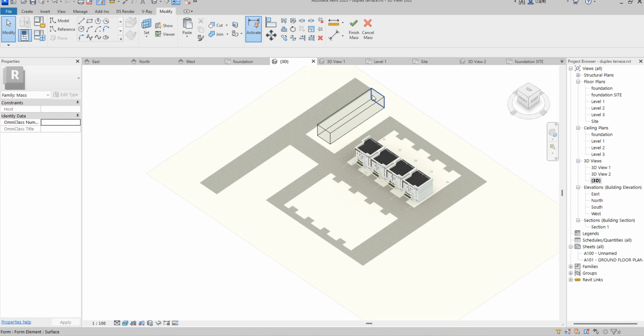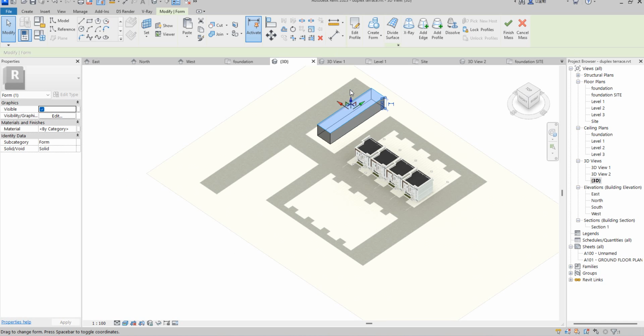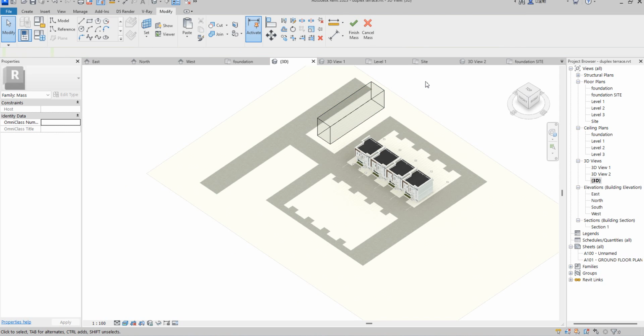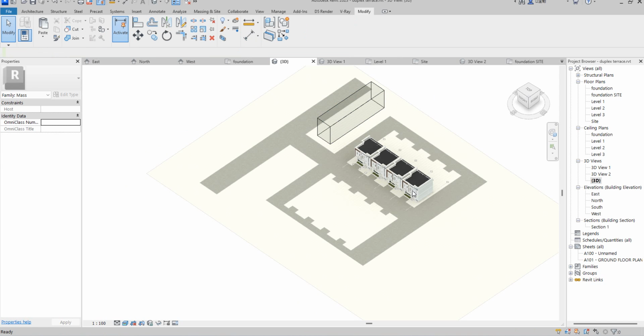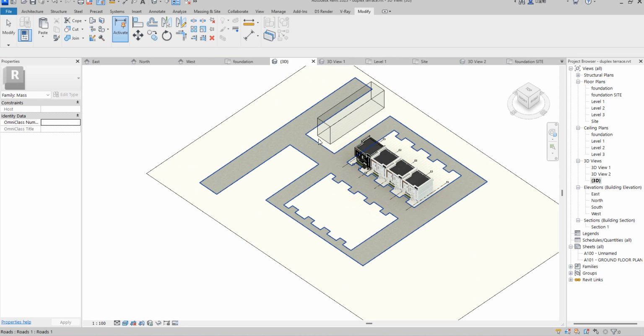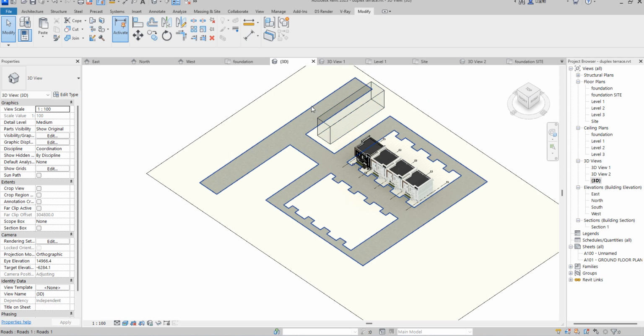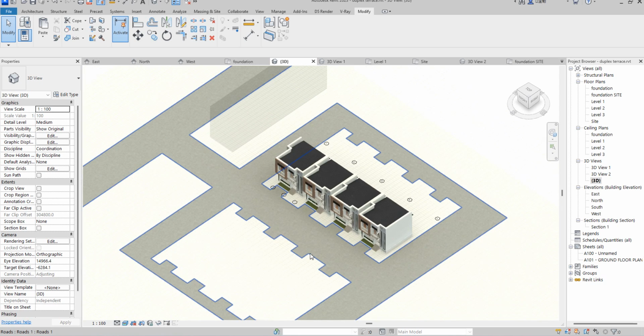So you have it in place as a normal drawing. You can decide to now be extruding them, increasing the height, the choice, your idea. So whatever you want to create is a form that you just have as an illusion to demonstrate things here. So we come to say finish. If you say finish, here you can bring whatsoever by just aligning a wall on it. You can just match a wall on the surface. This wall will be there and everything will be intact without you having any issue.